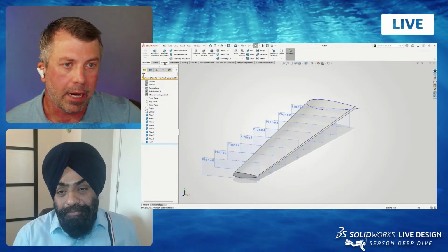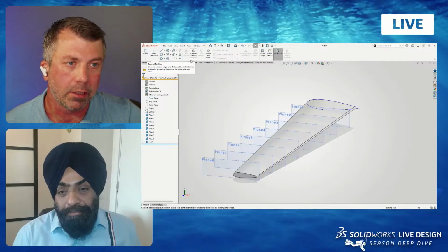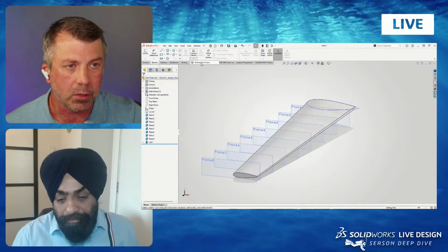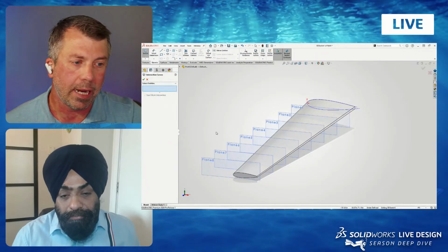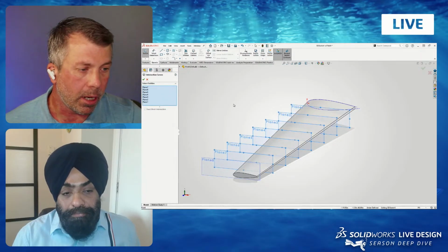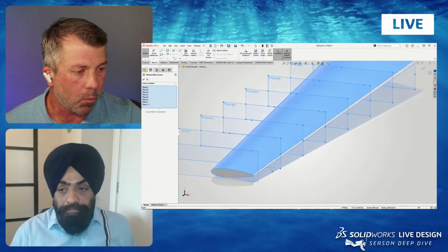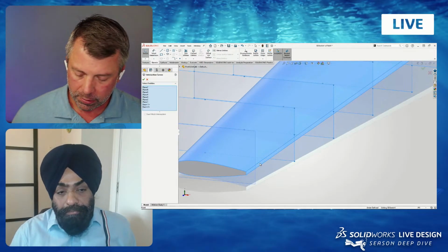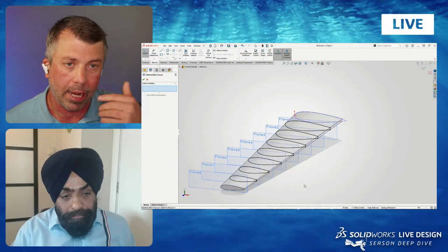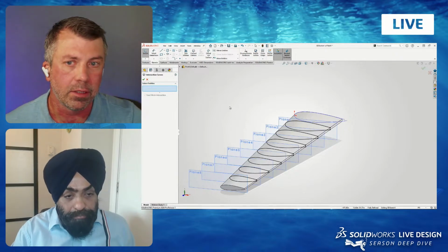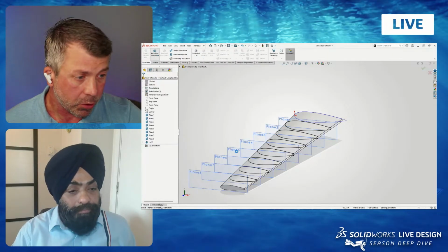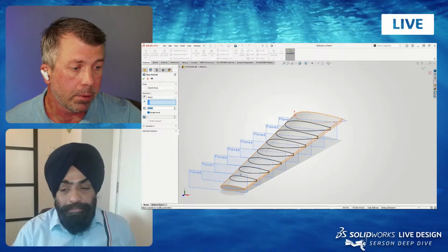All right, so what I want to do now is create a new sketch, and I'm going to do a convert entities. And under convert entities, you have this intersection curve. This is such a cool tool. What this does is says, hey, anywhere we have planes or other surface bodies or solid bodies that are intersecting, I want you to produce a curve. Let's go back to create an intersection curve, and just like that we can produce all of the geometry for our ribs. And then from there, extrude boss, I'm going to go ahead and grab every one of these.